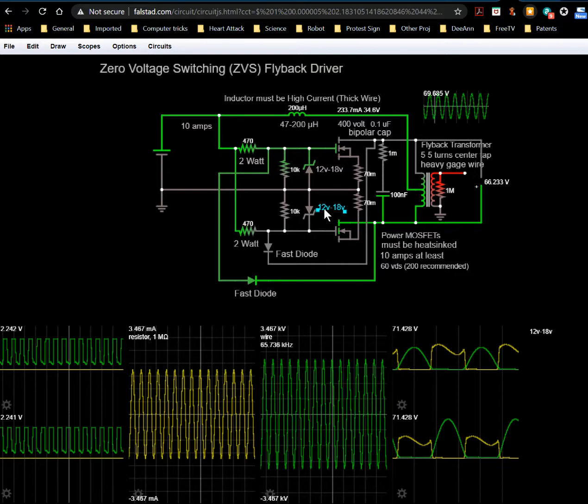that's basically keeping this thing essentially off, because the voltage is too low. The voltage needs to be much higher to get good conductivity out of this thing. So it's essentially off at this point. Whereas this voltage is, look down here, it's at 12 volts. Okay, and that's because we got this 12 volt reverse bias Zener here. So it's acting like a little bitty regulator. So it keeps that to 12 volts and no higher, so that this doesn't blow these FETs out, because it's a no-no to usually put more than 15 or 20 volts across the source gate of a FET. They're kind of sensitive to that.